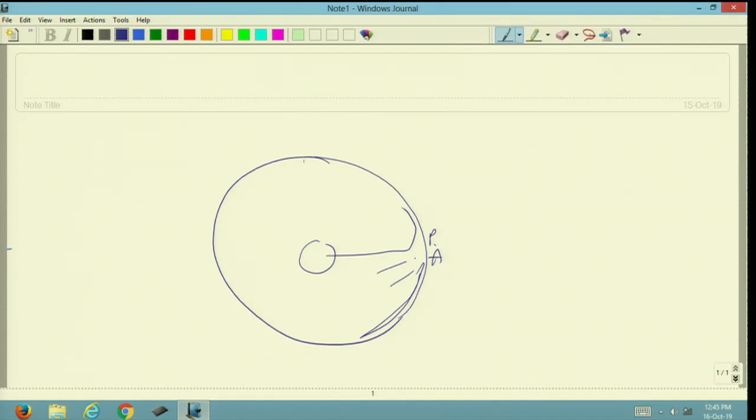Now, this gap has been there after one rotation of P. So, as it moves forward, now these fibers are being delivered continuously. So, this gap is going to be filled by this newly fed fiber, and then as it moves still further, you have a new layer here followed by the old layer. So, as it continues rotating, you will have a single layer of new fibers, followed by that single layer being deposited onto the already existing layer of fibers.